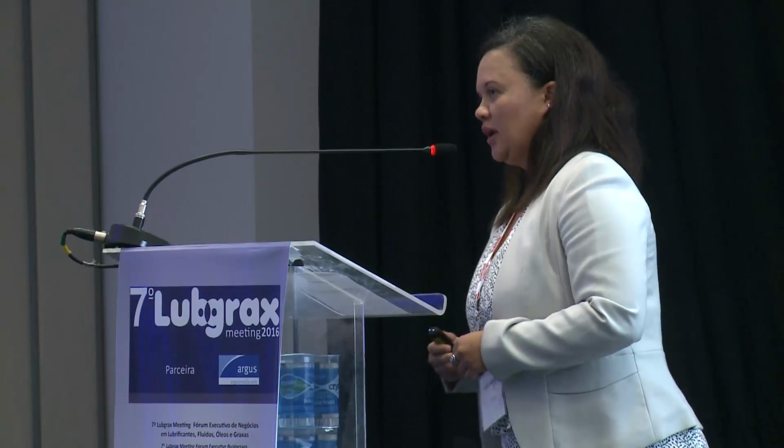Great. So I specifically took 2 grades of the new products and tried to make some greases with them. These were the base oils used. In the first column, I have the solvent neutral, the SN 500, and the 2 NYNAS range products at 100 and 120 centistokes. There you see that you get the benefits of a good pour point. There is a slightly lower viscosity index, and the flash points are also probably a bit lower than what you might expect.